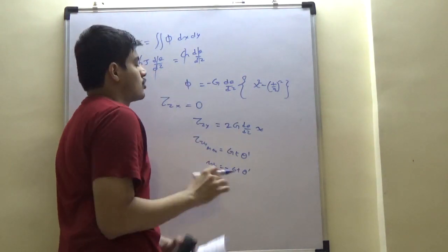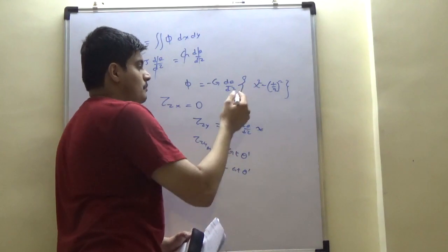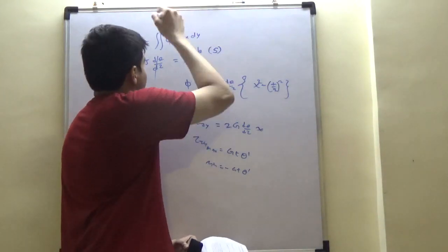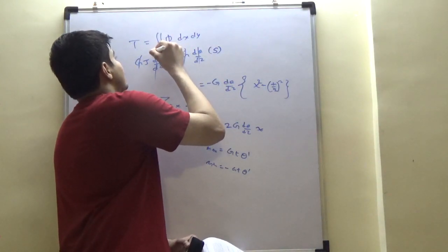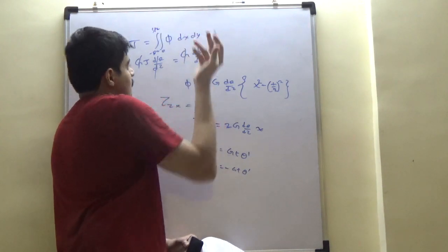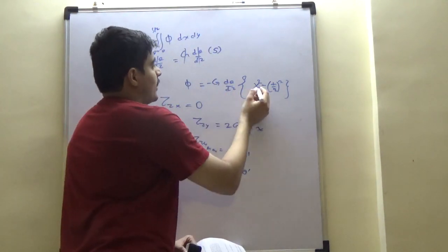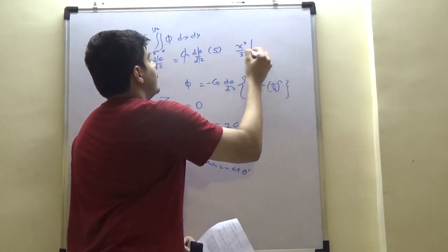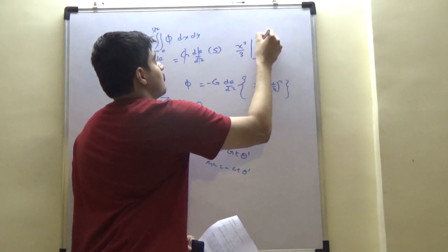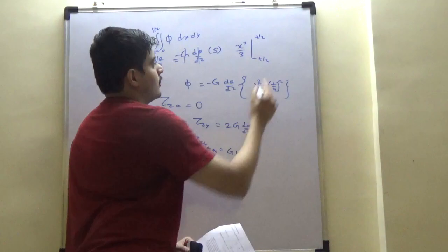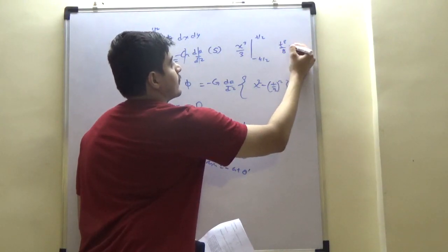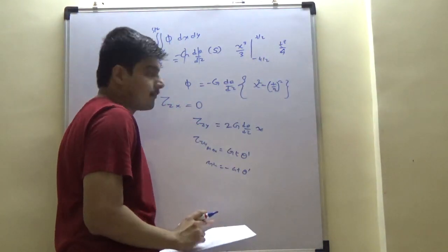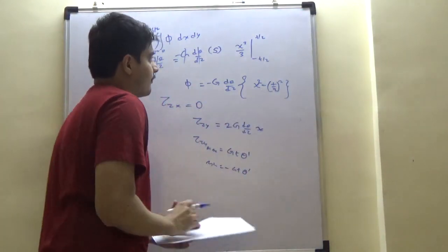dy is invariant, so y is going to go from minus s by 2 to s by 2. So s is going to be here, right? The length, because dy goes from minus s by 2 to plus s by 2. So s has come out anyway, I know. So x square integral is going to be x cube by 3 from minus t by 2 to plus t by 2. I am keeping minus sign here, right? So t cube by 8. So t cube by 4 this will be, because both will get added, a minus b minus a minus b. So t cube by 12, right?